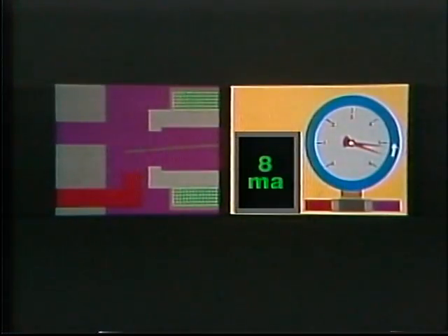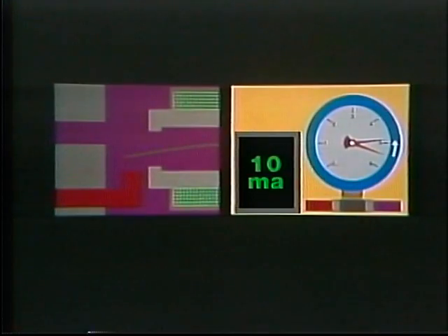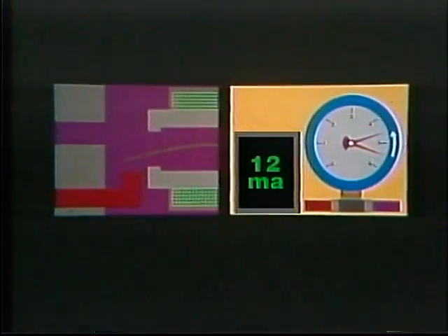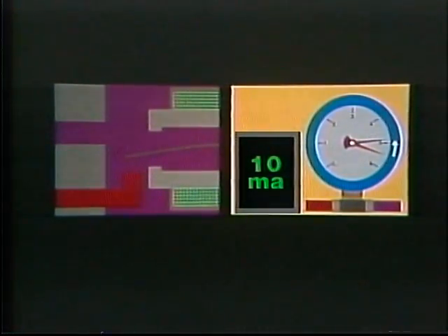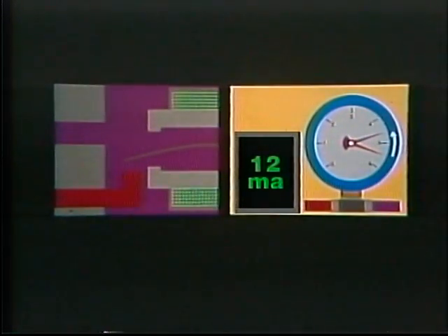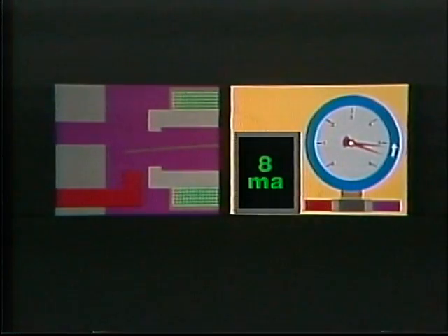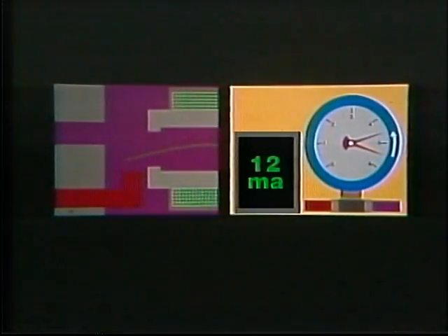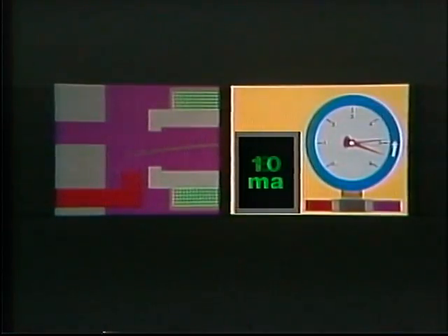Here is closed-loop fluctuation, from 8 milliamps increasing to 12 and decreasing to 8. In these pictures, exaggerated for clarity, the plate is always moving slightly toward the inlet and away from it, changing the pressure drop slightly, the result of changing current to the pressure actuator. With engine warm, with oxygen sensor hot, look for actuator current to change back and forth in a narrow range. Closed-loop fluctuation is normal, averaging to maintain lambda 1.